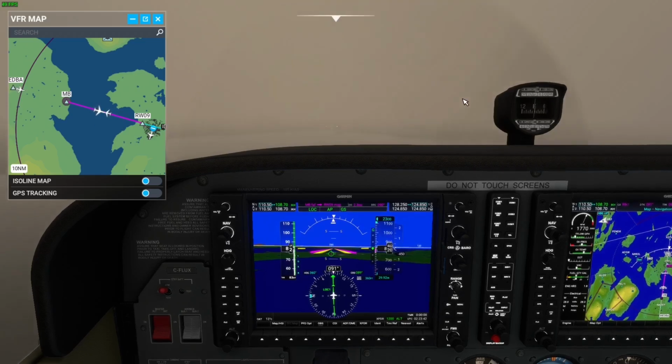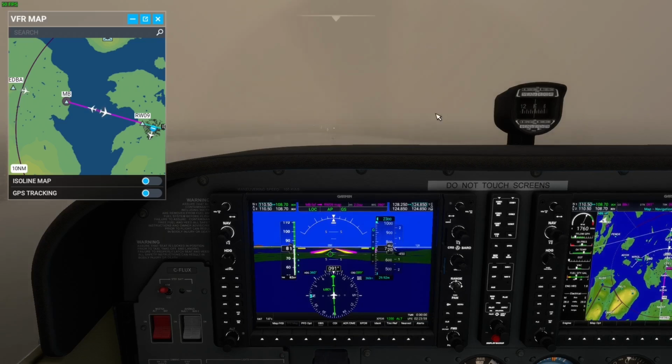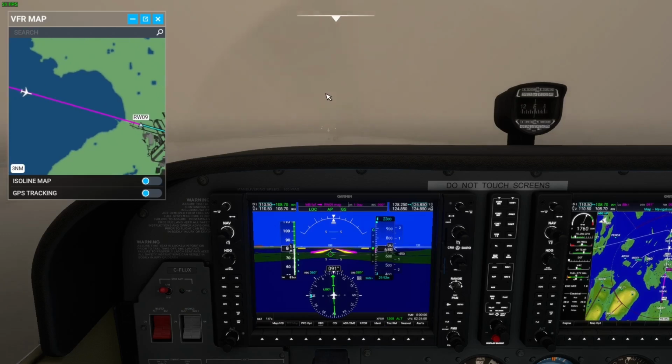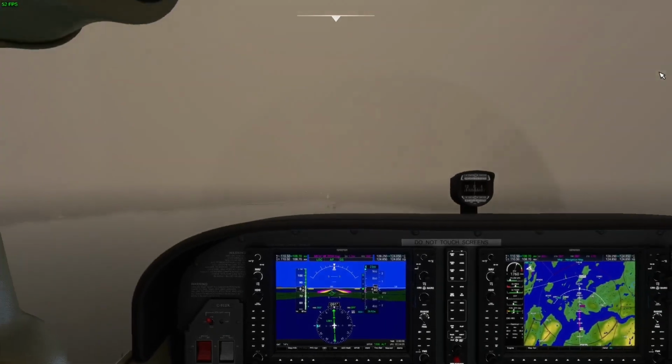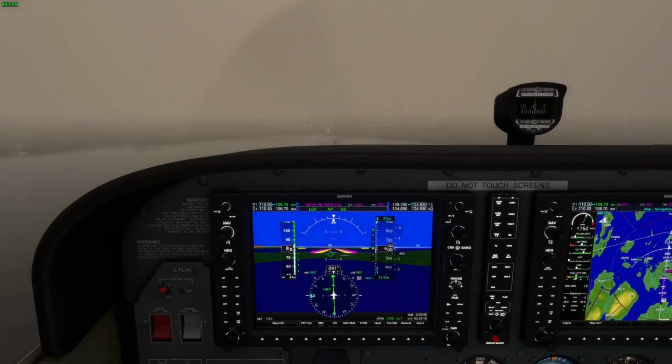and I can just start to see straight ahead of us the strobes at the end of runway 09. So pretty soon we'll be visual. However, because we're on the ILS and it's doing a better job than I could, we'll continue to keep the autopilot on and fly the ILS closer to the ground rather than change over to visual. So we're still landing on instruments even though I can see where I'm going. So we'll bring it down to where we're almost over the threshold, and then I'll kick out the autopilot, take over manual control of the aircraft, and do a normal landing.